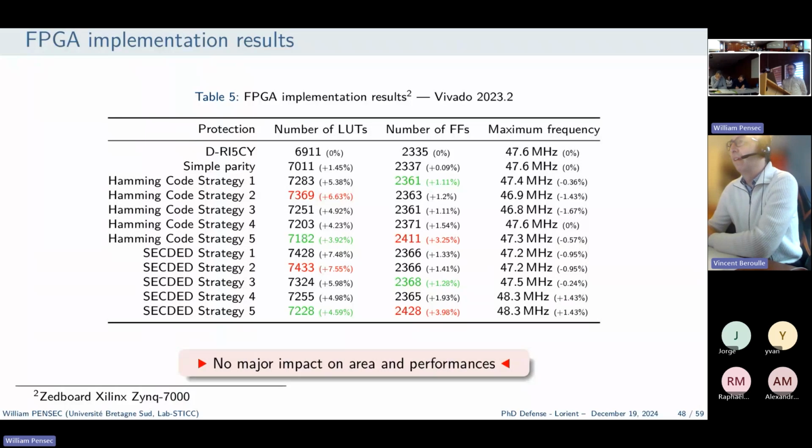Yes, I also have a question. I think Bettina already asked a question on FISA, but I have another question also. I am wondering if in your implementation of FISA, you implemented a specific solution to improve the fault simulation time, because of course, when you have so many faults to inject, if you make no improvement, you will have to compile all the faults. You will have to simulate all the clock cycles for each fault. It will take a lot of time, and so I would like to know if there are some improvements inside your FISA architecture to avoid some useless simulation clock cycles, etc.